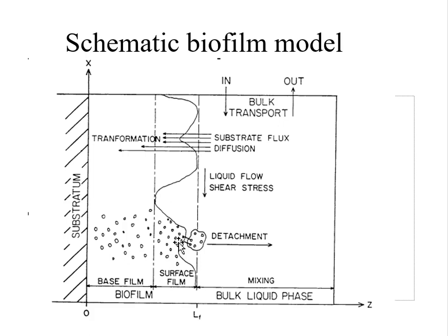And in those filters, there is very little shear stress. So the biofilm essentially just keeps getting thicker and thicker. And eventually, you have some type of catastrophic event. It can be that you get this sloughing event all the way from the bottom, releasing large sections of biofilm, not small pieces like here, but large sections. And these sections can then clog the filter, and you have an accelerating problem.